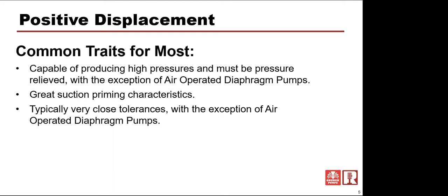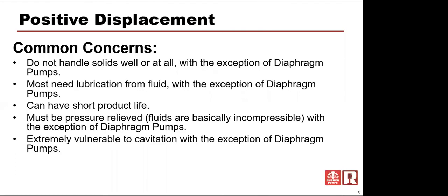They have great suction priming characteristics almost always, meaning that they can prime themselves even from below pump level quite often. Typically, they are very close tolerance, again, with the exception of air operated diaphragm pumps. They cannot handle solids well at all, with the exception of diaphragm pumps, which can handle some. Most need lubrication from the fluid. Some, like gear pumps, for instance, wouldn't even operate on water because the lubricity of water is too low.